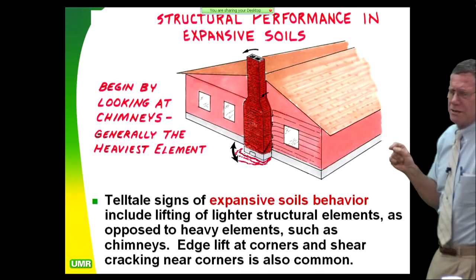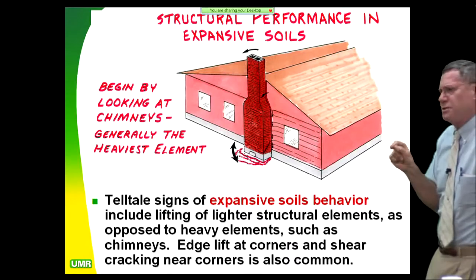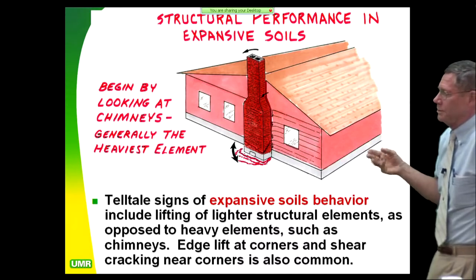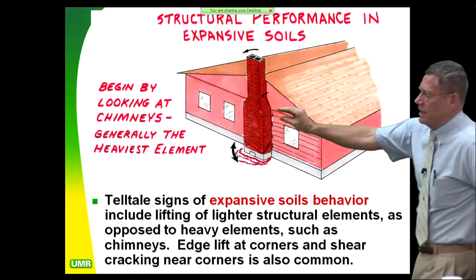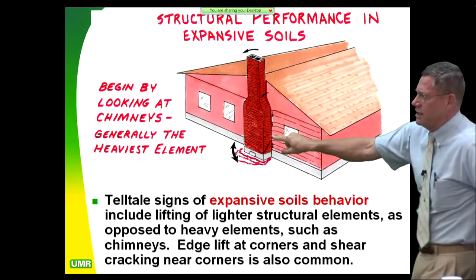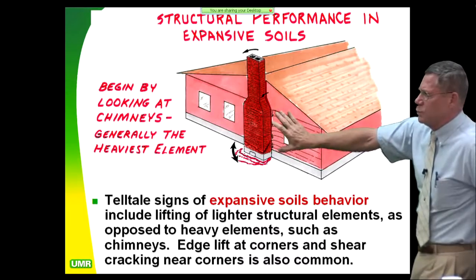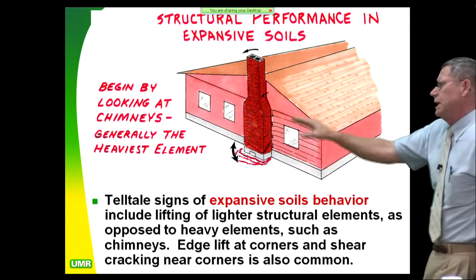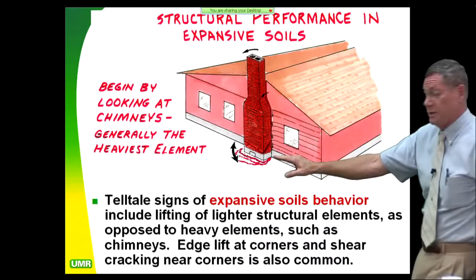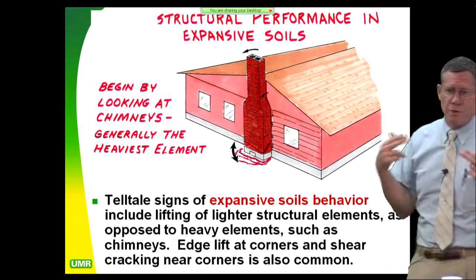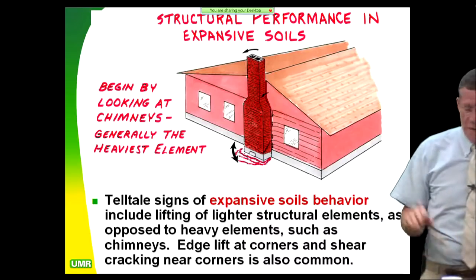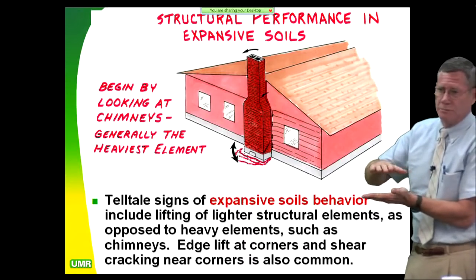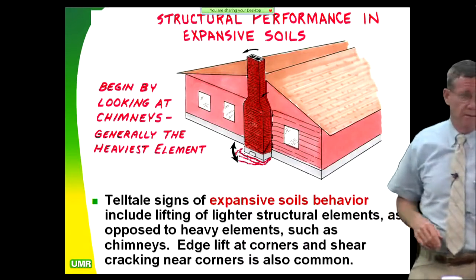Wood shrinks in cross grain significantly: 6% in cross grain over a period of years, and 1.5% in longitudinal grain. So if we look at an older house, these wood elements are going to shrink, and you're going to tend to see movement here that's due just to wood frame shrinkage, especially if you've got double headers on the top plates and on the sill plates. And so it's not all due to expansive soil necessarily. You do have to look at the framing system that they've used there. And if they're double plating, like with two 2x6s, you can have a half inch of settlement long term due to cross grain shrinkage. And that's a lot if you're going up against